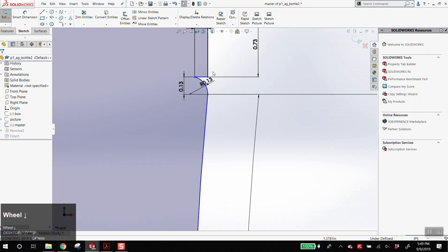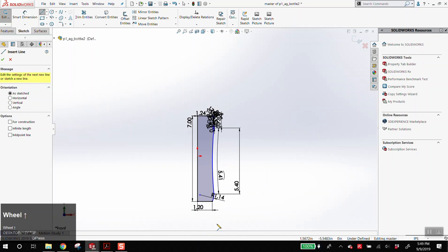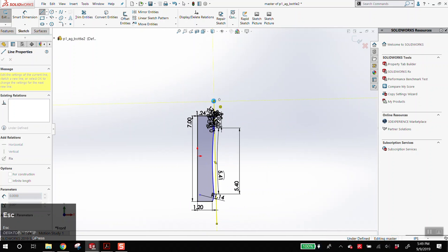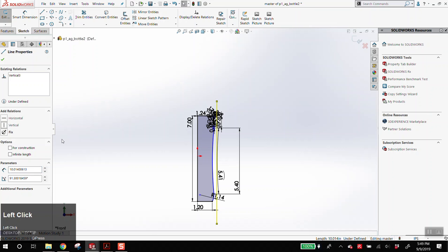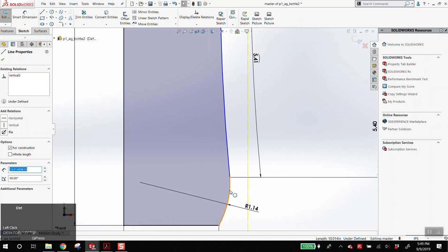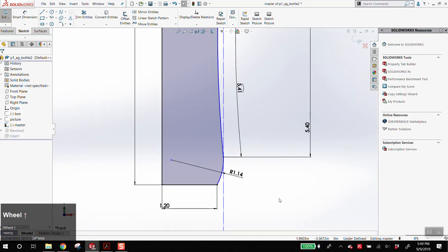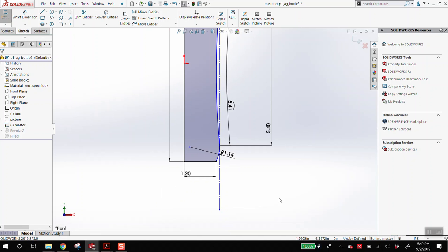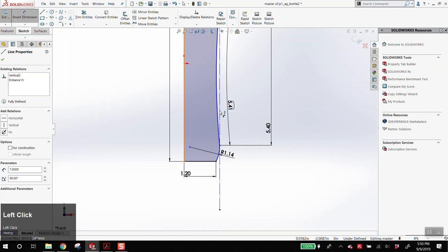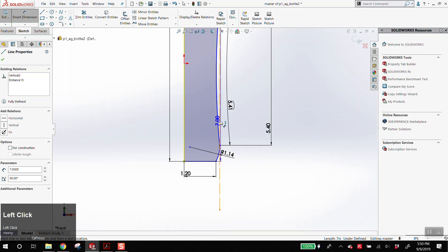What Max was saying, I believe, is let's say you determine that, I mean, you could combine both methods. So here is a line, we want it to be vertical. I kind of goofed that up when I drew it. So I select the line, I set it to vertical, I set it for construction. I can now select the line and select this arc, and I can say make this tangent. This is where it'd be good to take the calipers and measure the width of the bottle. But let's assume that your trace is correct. I can hold this line in place by dimensioning from the center line to this outer edge.